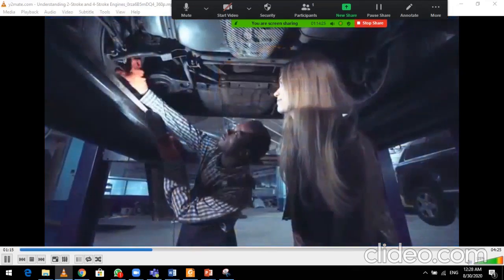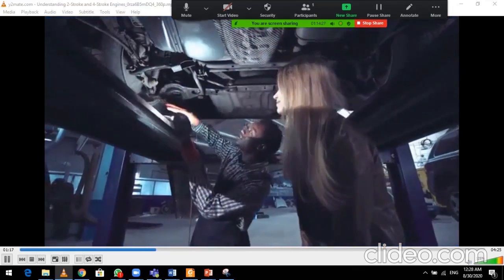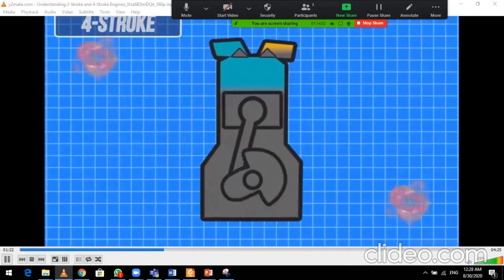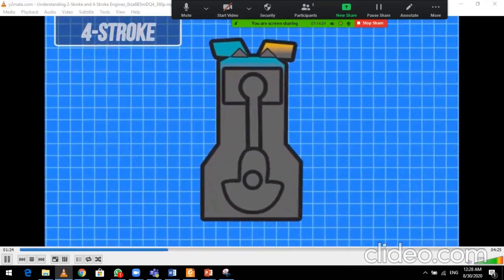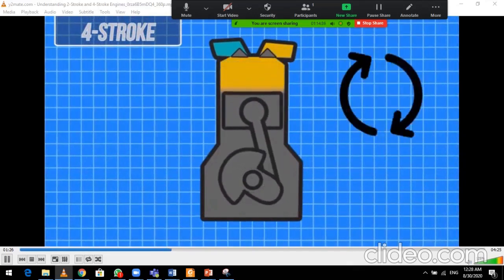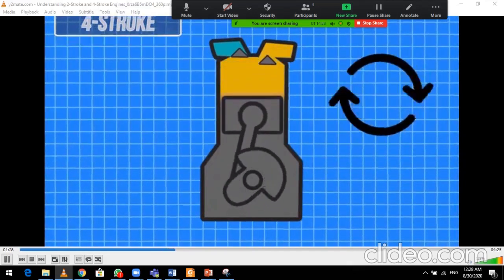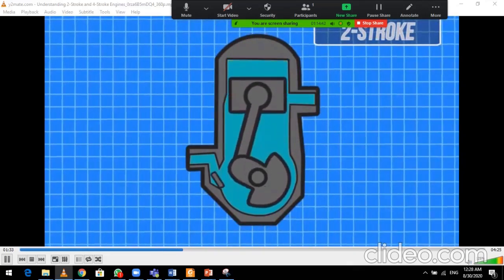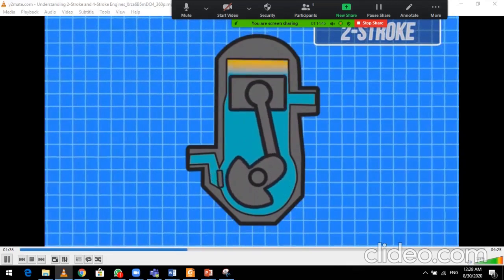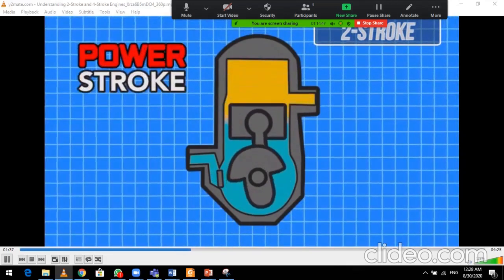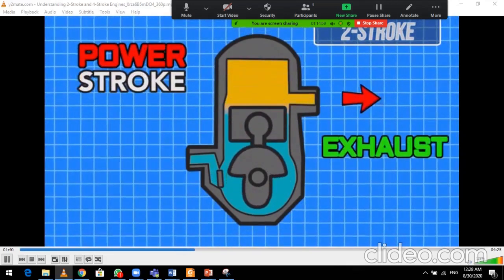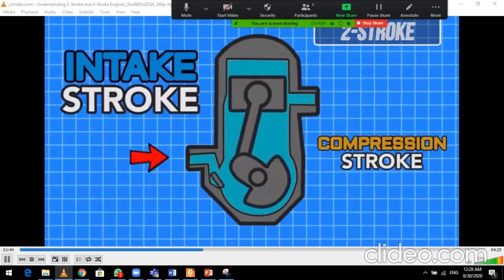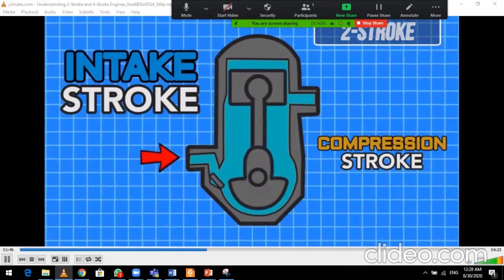Examining this process closer yields the observation that the whole cycle is powered by the initial combustion stroke. This means that the combustion of the fuel mixture needs to impart enough power on the piston to allow it to rotate the crankshaft twice. A two-cycle engine, on the other hand, has much simpler mechanics, as it basically consolidates the different processes of a four-stroke engine. There is a power stroke, which also releases the exhaust after a certain amount of travel. Then an intake and compression stroke that draws in new fuel and completes combustion.